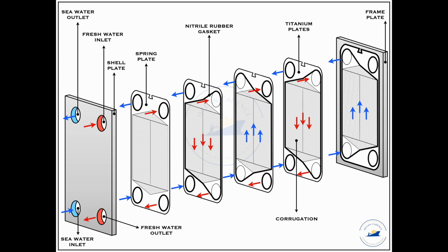It is also important to know that excessive tightening should not occur at any point of time. As I already explained, if the plates are squeezed too much, then there can be deformation on the plates, they can squeeze out, slip out, and this can not only alter the heat exchange efficiency but can also create loss of fluid and leak of fluid in the heat exchanger medium.